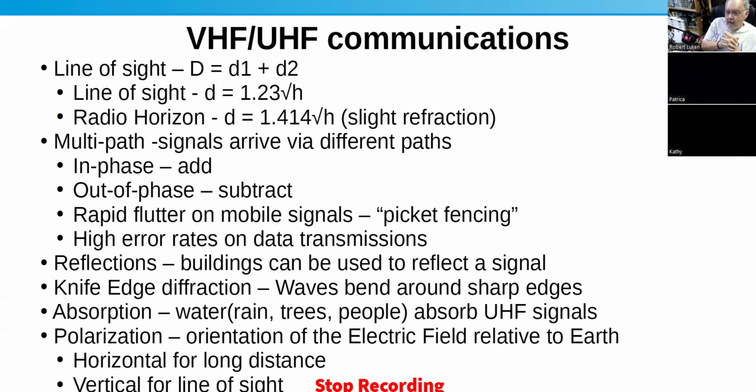And we've mostly talked about just straight line of sight between two, say, handy-talkies, but you have the same issue when you're talking to a repeater. And most repeaters, I don't know of any that aren't, in the VHF, UHF, are going to have a vertical antenna, so they'll be vertically polarized. So if you're trying to talk to a repeater, you need to hold your handy-talkie straight up.